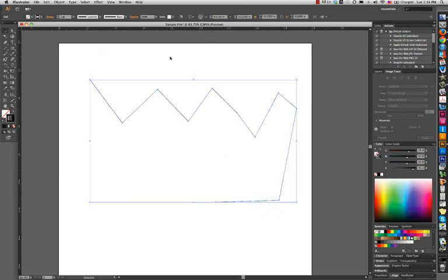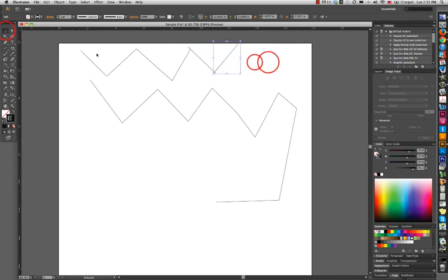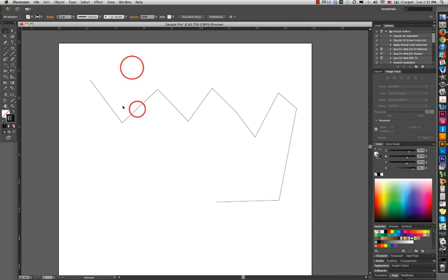When I go back and select this object, it now is selecting as all of these line segments together, whereas before, if I were using the line tool, these line segments would be drawn separately and they wouldn't necessarily be connecting at the end, so I might have kind of ugly or messy connections between lines. So if you're going to draw something that has multiple parts, use the polyline tool.